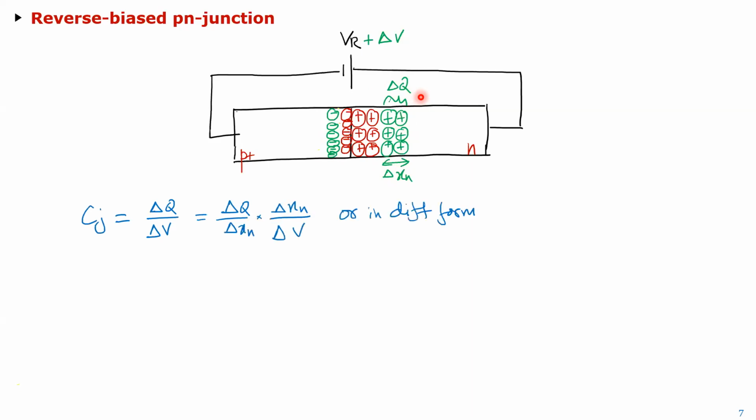So essentially what you're trying to find out is this nonlinear capacitance. If you look at it as a differential capacitor, or an incremental capacitor, in the sense you give a certain reverse bias voltage and you change a tiny amount of the voltage and you see a tiny amount of charge go into the node. That basically tells you what the cap is.